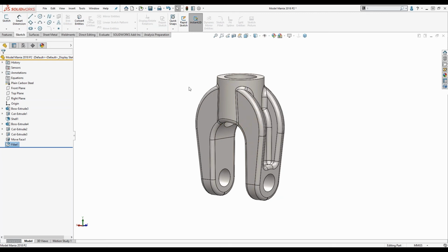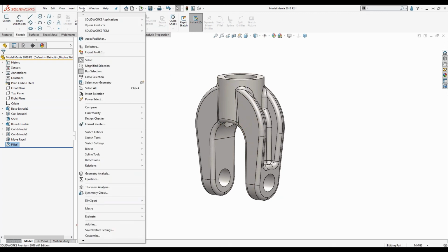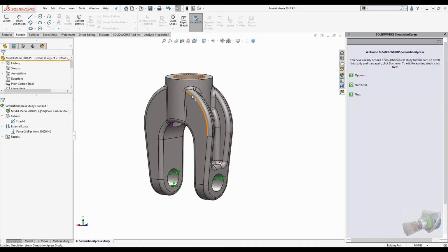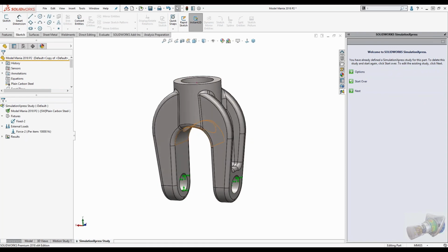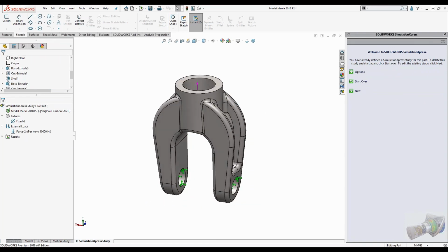And now we need phase 3, which is with Simulation Express. If you don't know about Simulation Express, it's a very simple product. It's free with all of SOLIDWORKS Standard, Pro, and Premium. It's under Tools, Express Products, Simulation Express. It loads in a simulation. It's very limited with what you can do with it, but for this case, for what they're asking for, it's the perfect option, right?